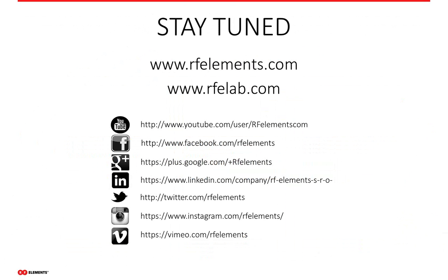Absolutely. With the use of any of our horn antennas, shielding is not required. The only shielding that may be required is on your radio. It depends which radio you're using. The radios are getting better; a lot of the manufacturers are moving away from cheap plastic and building metal cases. But as far as the antenna itself goes, it's inherently shielded.